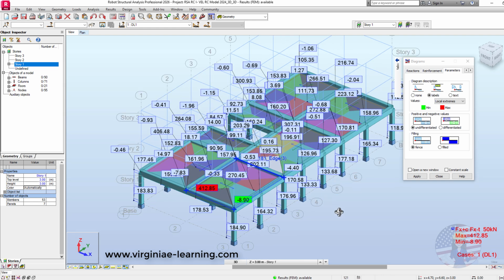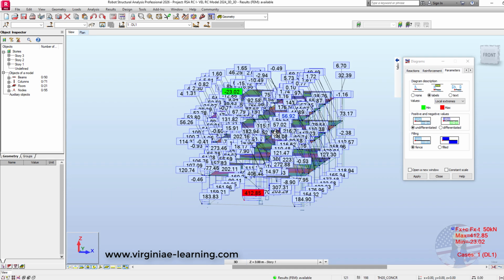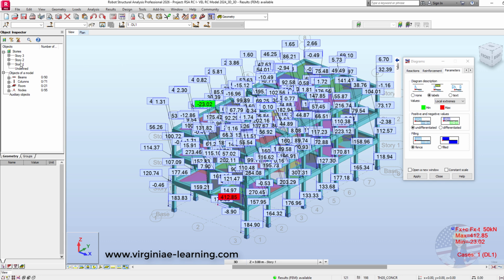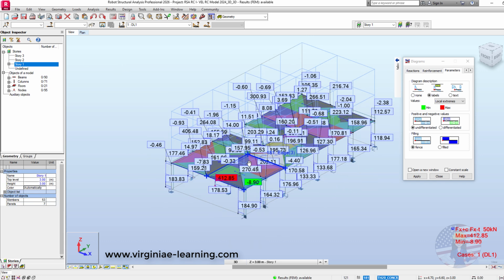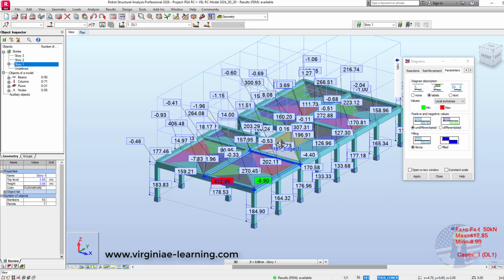Again, this is the kind of issue we want to catch early in the design stage, not once the model is already undergoing detailed analysis. In this case, for example, we've already assigned multiple load cases and combinations to the model, and so far we haven't identified any issues that might compromise the integrity of the structure, or any of the concrete members for that matter. However, we've yet to assign seismic, wind, or other dynamic loads. In fact, we could say this is still an ongoing project, and more structural elements may be added as the design progresses. This means that, while the model appears sound at this stage, we're not entirely free from the risk of unexpected behavior as the structure continues to develop.